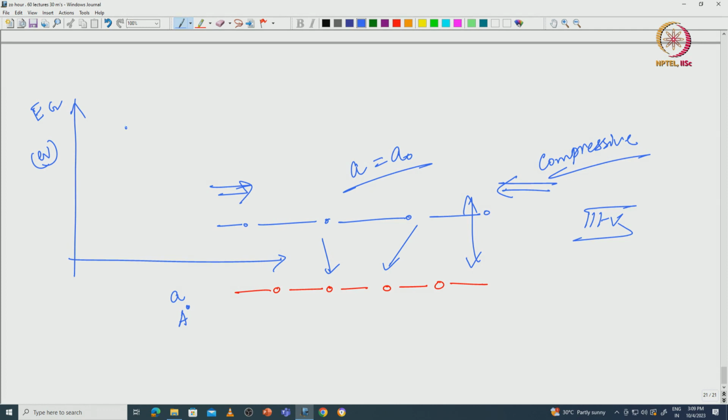So for instance, gallium arsenide could be here, okay, indium arsenide could be here, and this goes like that. So if you go from gallium arsenide to indium arsenide, the band gap will change like that. Okay, indium phosphide could be here, for instance, just telling you an example. What this line means is that when you have indium gallium arsenide, it's a ternary alloy. A ternary alloy means that there are 3 elements, indium, gallium and arsenic.